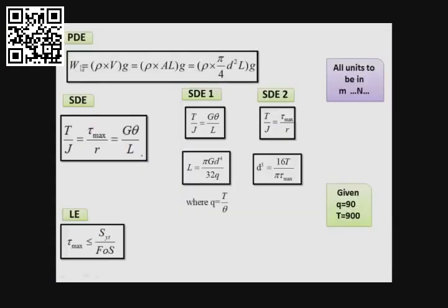First thing we need to do is form the primary design equation. Here, what do we need to optimize? Weight. That's why the weight equation is the primary design equation. W is equal to, how to calculate the weight? Mass into G, acceleration due to gravity, M into G. M means rho into V, rho is density and V is the volume.